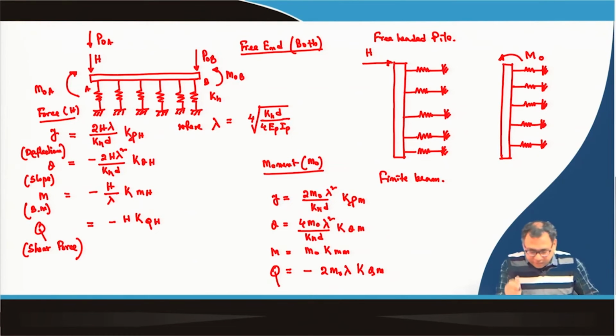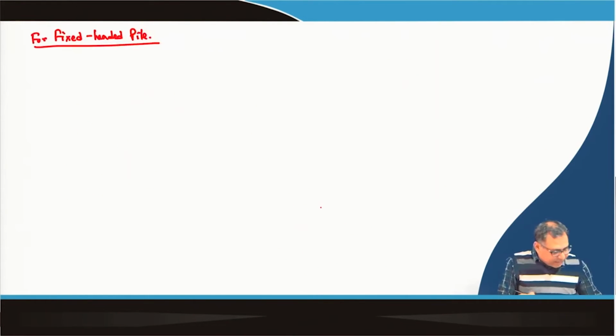So, for the fixed headed pile, what to do? The equations for the free headed piles can be used if we apply a fixity for the fixed end.